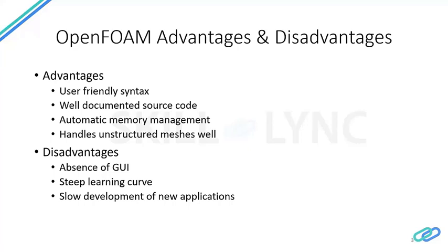The main disadvantage that OpenFOAM has is its absence of a GUI. Its competitors such as ANSYS Fluent or COMSOL have the advantage that you can choose an option, a button on your screen, and can change particular values. But in OpenFOAM, you have to specify your control variables. OpenFOAM solver package has a steep learning curve as well. By this, I mean you need to be well versed with the programming language structure and basic CFD, basic fluid dynamics.